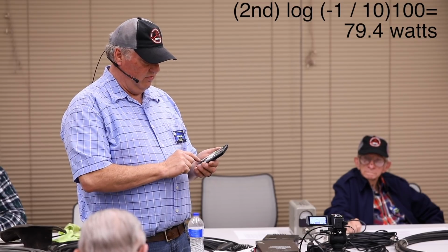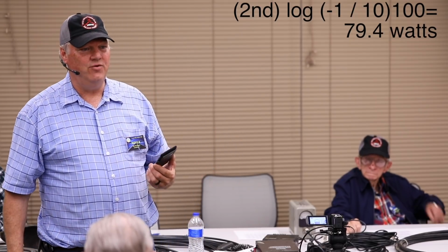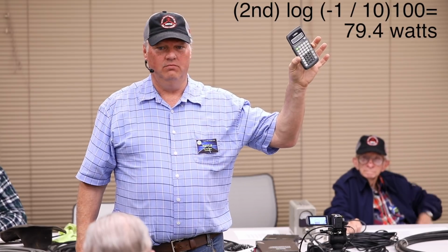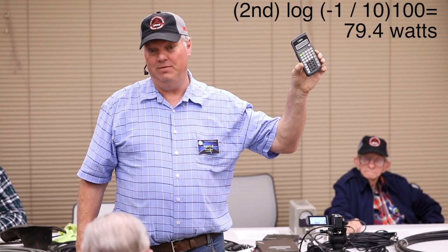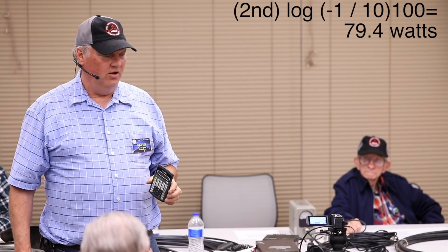So on that cable, I lost 1 dB at 100 watts, right? It's about 79.4 watts that gets to my antenna. You lose about 20 watts in that 100 feet of cable at 1 dB, because when you're measuring things, I use dB as a reference.